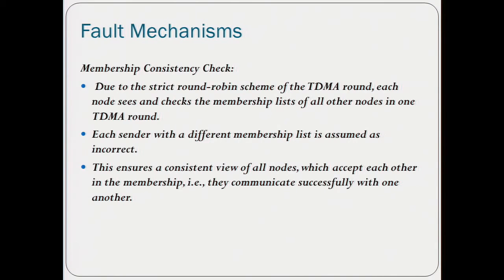Another model that can be taken into consideration by this scheme is the so-called bubbling idiot. The bubbling idiot model says that one node keeps on talking all the time and doesn't stop. How do you determine that you have a bubbling idiot in your network?